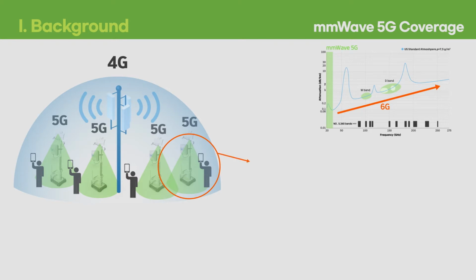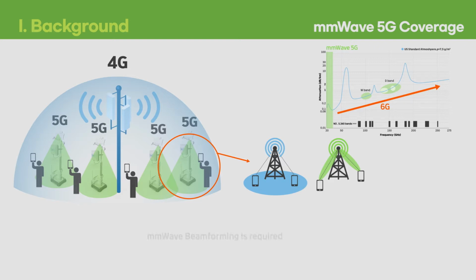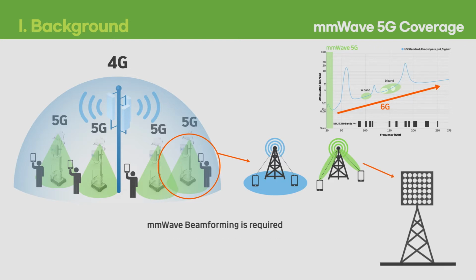To overcome the intrinsic loss and maximize transmission efficiency, it is necessary to reconsider how to transmit and receive the mmWave waves rather than spreading EM waves omnidirectionally. Thus, a specific technique is required to focus radiation fields or control the directivity of the EM waves. This technique is called beamforming, but to realize the beamforming technique, the antenna configuration must first be changed.